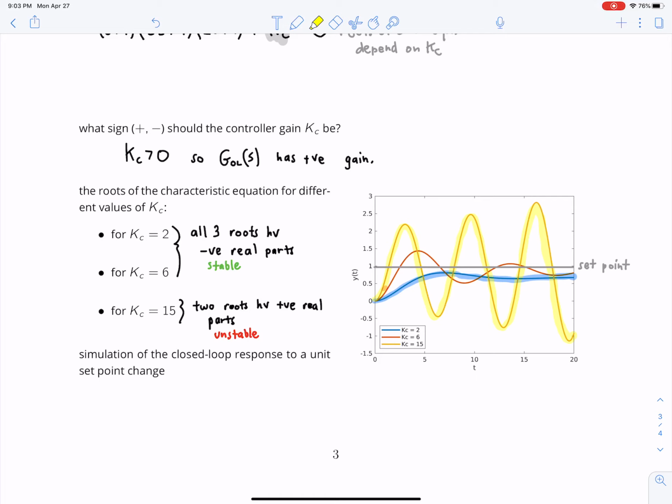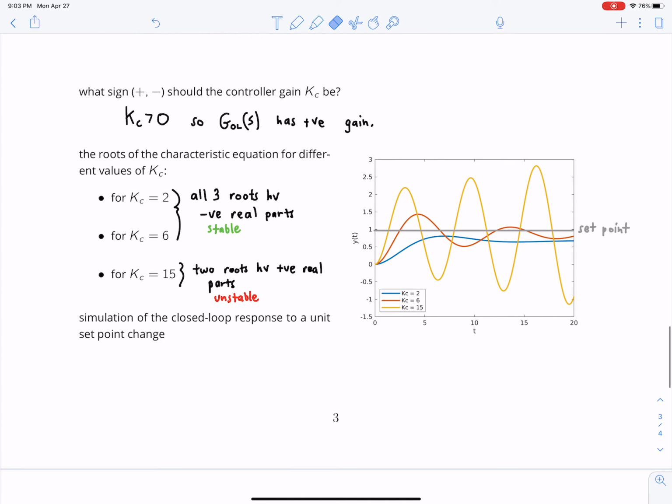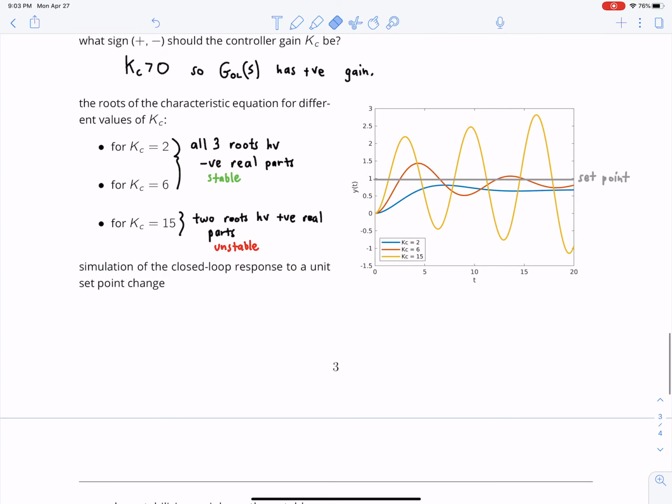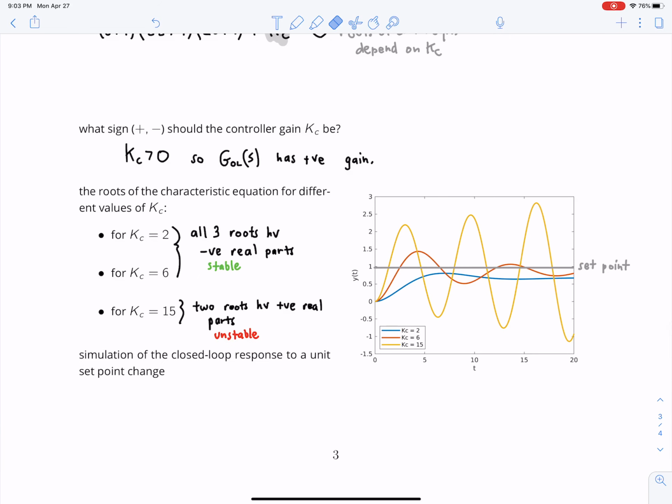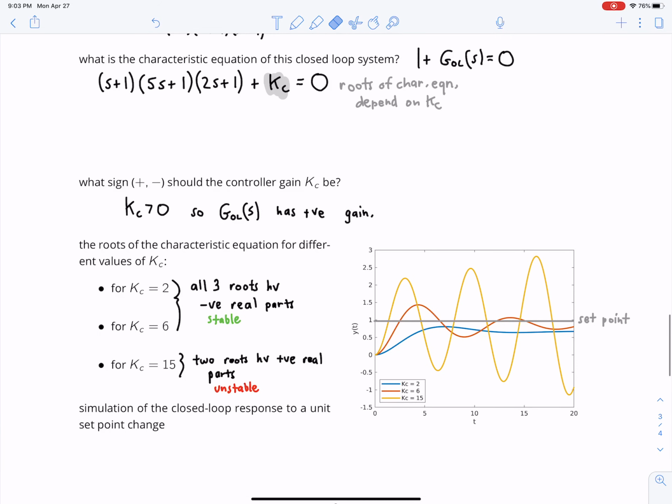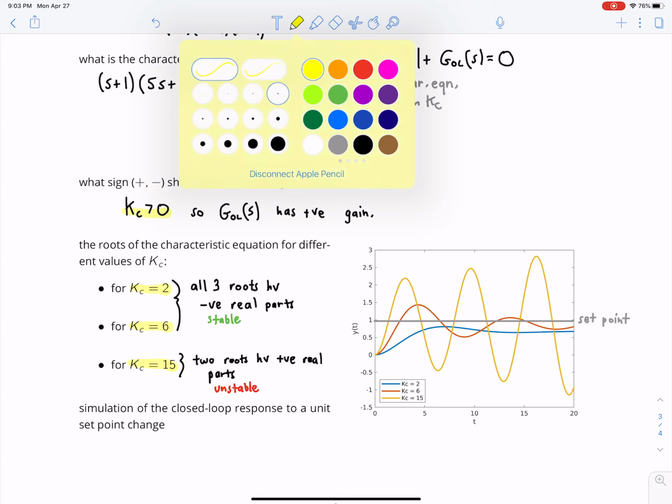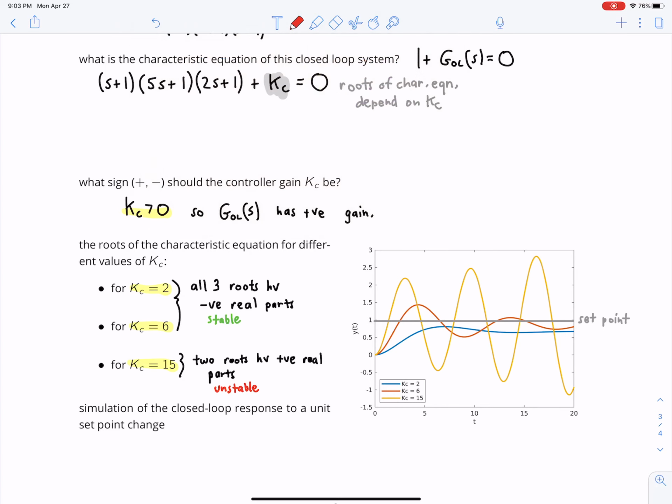And so in practice, what will happen is the control valve will fluctuate between fully open and fully closed. And that puts attrition on your control element. And obviously, it's not good for the set point change. So this is a nice simulation. It shows us indeed we can choose Kc of the correct sign. So note these are all greater than 0. Okay, so Kc greater than 0. We'll put a little check mark.